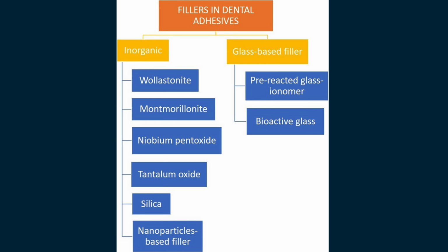1. Mechanical reinforcement. Fillers improve the elastic modulus, bond strength, and durability of adhesives. A reinforced adhesive layer forms a stronger hybrid layer that resists degradation and crack propagation. 2. Improved physical stability. Filled adhesives exhibit increased hardness, reduced water absorption, improved dimensional stability, and lower susceptibility to hydrolytic degradation.